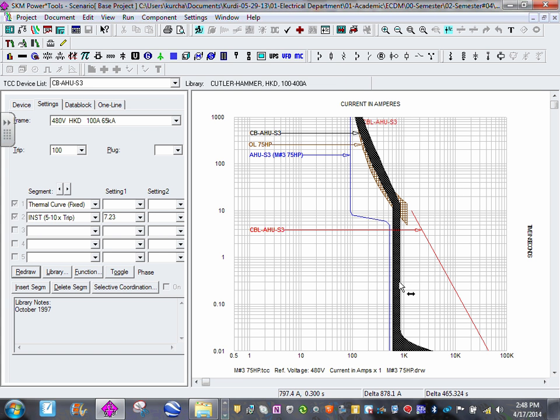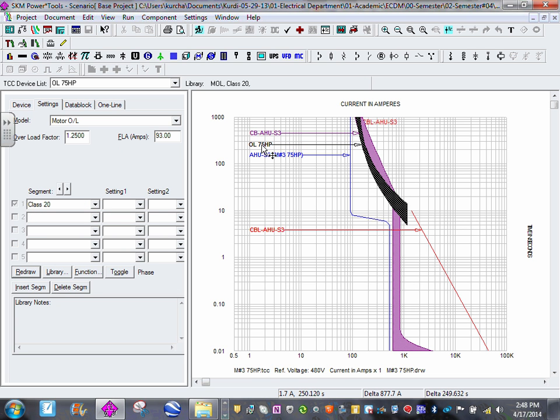The full load current was 95, and I went just above it, even better than the overload. You can also show the overload protection right in here. This is good, especially for engineers doing the branch circuit. Guys, try instantaneous trip circuit breakers, specify them with major equipment, and then you can check and size them based on SKM, and you can tell that most likely, granted everything is okay, which typically it is.